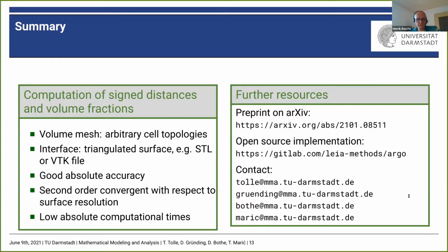I don't think your plan was ever to have a sharp interface. At least for VOF, you wouldn't get such a thing. It's never 0 and 1, and with some cells you're never going to match the volume, so you must have some cells with fuzzy volume fraction.